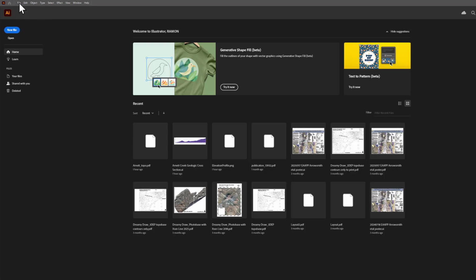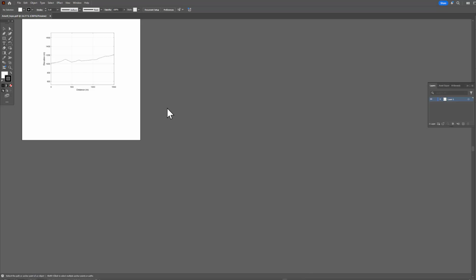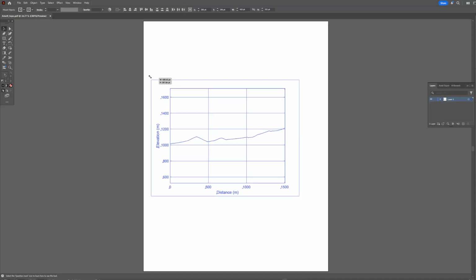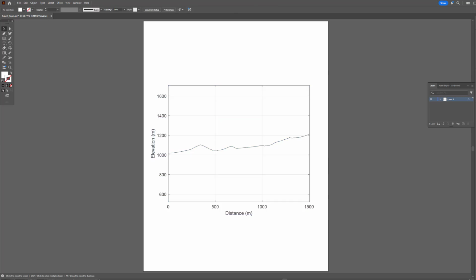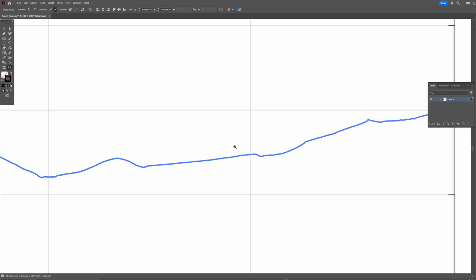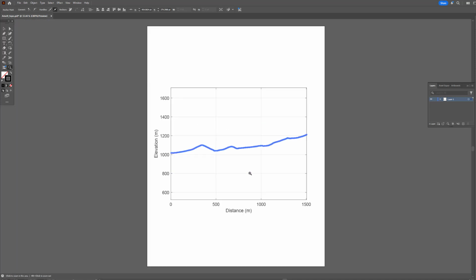So now if we go back to Illustrator, I can open the PDF file that I just produced. And again, I'll do Control-0, select all, Shift, and scale it evenly in both directions. We don't want to deform it. I can get my A tool, and there's a little white polyp thing in behind. So you can clean this up, but the most important thing is if I click on this, you see that topographic profile is now editable, and it's very accurate, so we don't have to click it out. So it's kind of more elegant in my opinion. Many points there that comprise that profile.